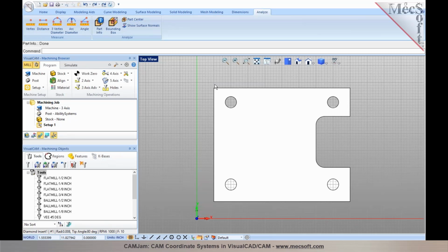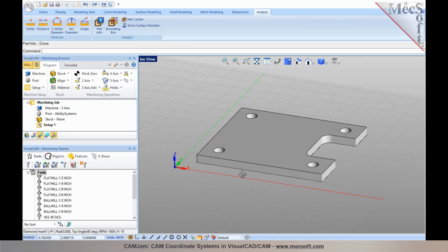The orientation is the orientation in which the part needs to be placed so that it is suitable for machining. In this particular case, you'll notice that the length of the part is parallel to the x-axis, which means the longer side of the part is along the x-axis and the shorter side is along the y-axis. If the machine tool you're working with has more travel on the x-axis as compared to y, then the way we currently have this part oriented looks right. So we don't need to rotate or do any additional transformations.